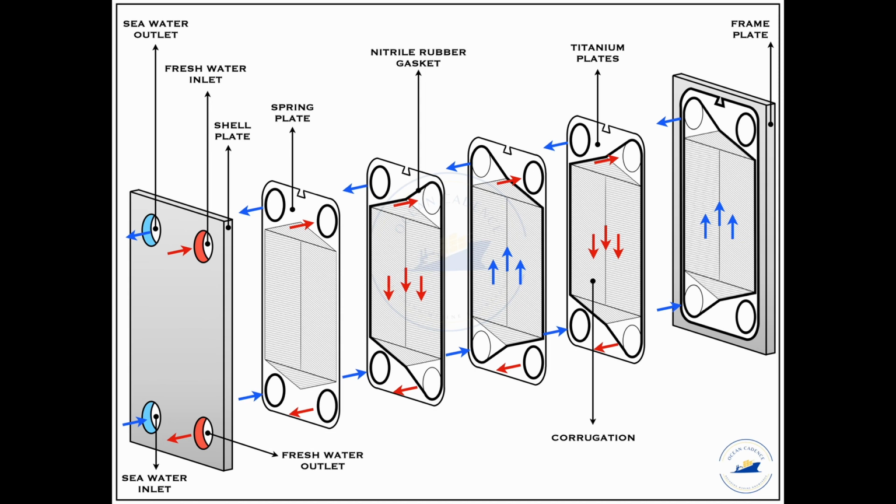If the heat exchanger efficiency is to be increased as per the manufacturer's recommendation, simultaneous addition of plates can be done. However, that has to be done only in case of service letters being received by the ship that are being sent from the manufacturer. It should not be done without consultation as it can lead to loss of fluid medium as well as untoward decrease in the heat exchange efficiency as well.